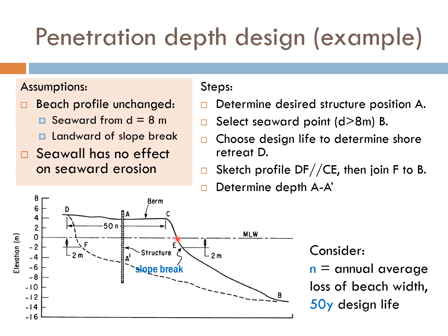So this portion of the beach profile is typically unchanged, meaning that under erosion, let's say the eroded profile is this one, then the shape of this part, which is landward of the slope break, remains unchanged. Only this part of the beach profile has changed.